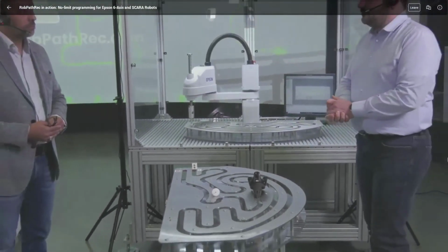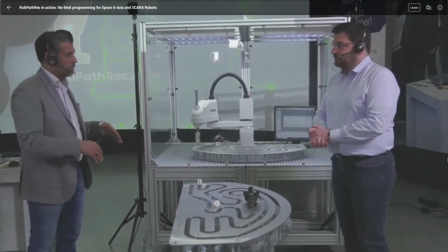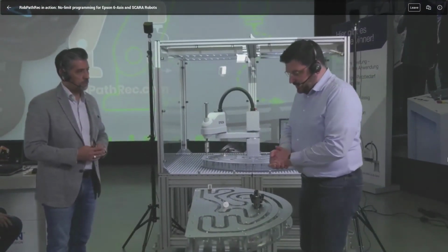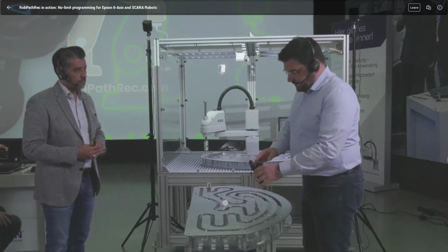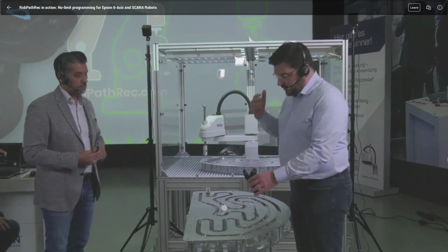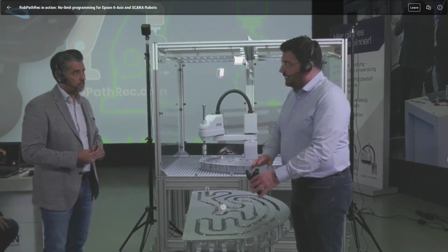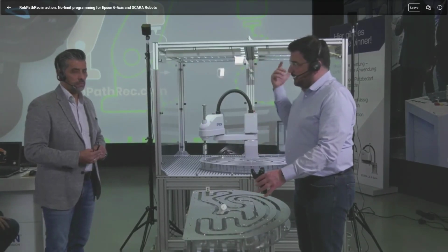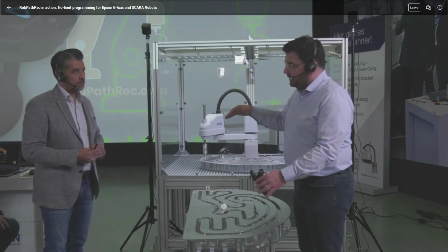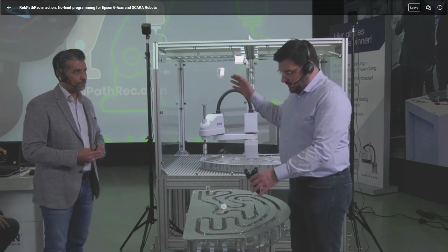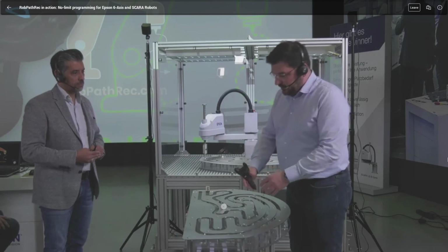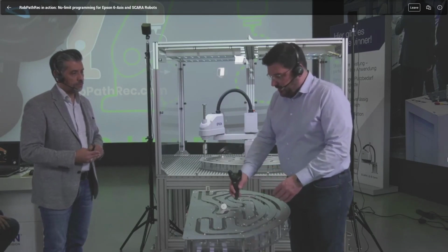Is there any restriction regarding the working area, for example, that the customer has to consider? Yes, you are right. Exactly. As you could see, I was just covering the clear sight from one of the laser sources to the tracker. This is one of the reasons why we are delivering two of them. Ideally, you can place them in an asymmetrical manner. That means one laser source will always have a clear sight to the tracker, and then it is ensured that you can make any kind of recording without interruptions.